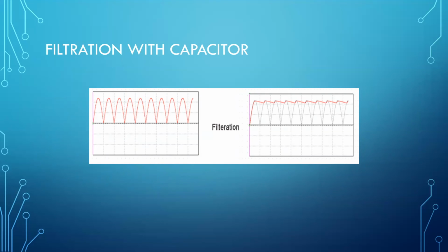Since rectification cancels out the negative part of the AC voltage, there are gaps of the voltage for certain periods of time. The capacitor fills in these gaps and regulates the voltage and supplies the voltage regulator with a steady flow of current, and this allows the phone charger to supply the phone with the correct amount of power. The process of filtration allows a conversion of AC to DC voltage.